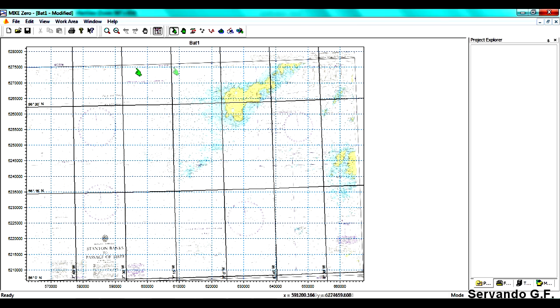As you can see, the format shape that the Admiralty chart adopted while georeferencing it now makes sense. Here, this is the upper edge of the Admiralty chart, and now it's parallel to this grid line that defines the map projection. So at this stage, we can tell that the image is correctly georeferenced, because the edges of the georeferenced Admiralty chart are parallel to those lines that define the map projection.